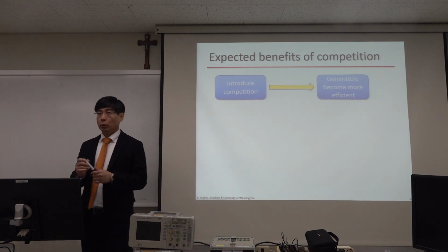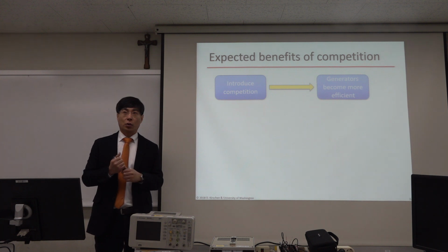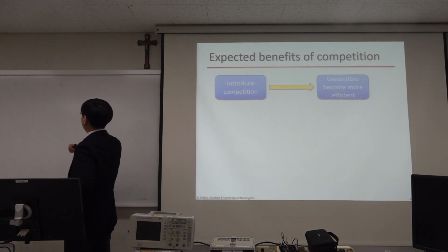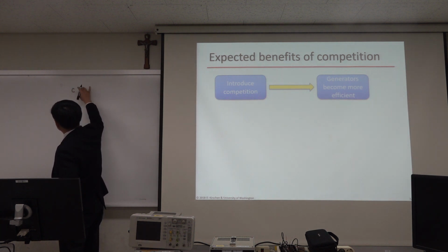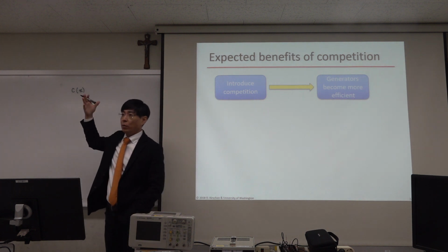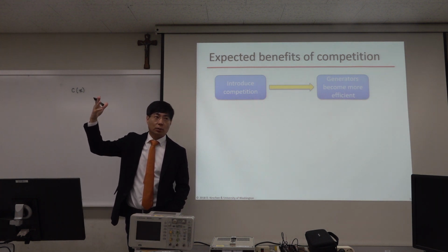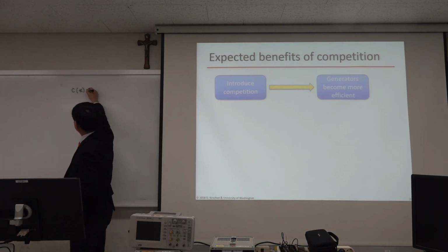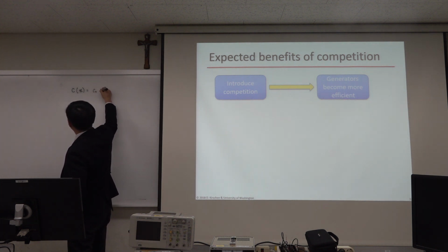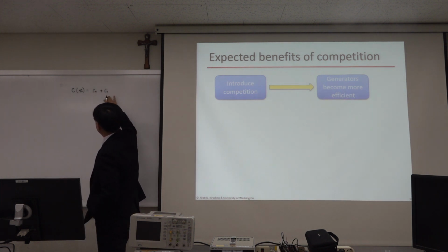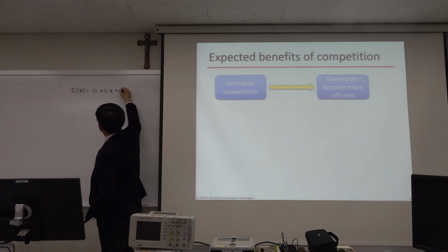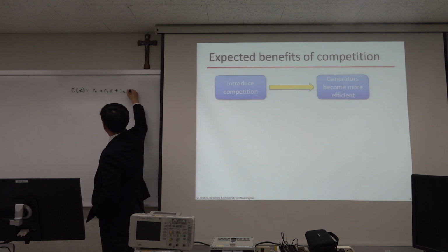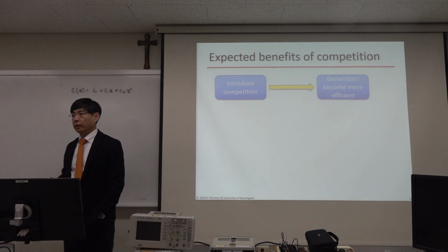Actually, later we will introduce the generation cost function. But let me write it here. Let's say C is the cost to generate. X is the power, measured in kilowatt or megawatt, and this is multiplied by some constant plus another coefficient which is proportional to the amount of power, and another coefficient which is proportional to the square of the amount of power.